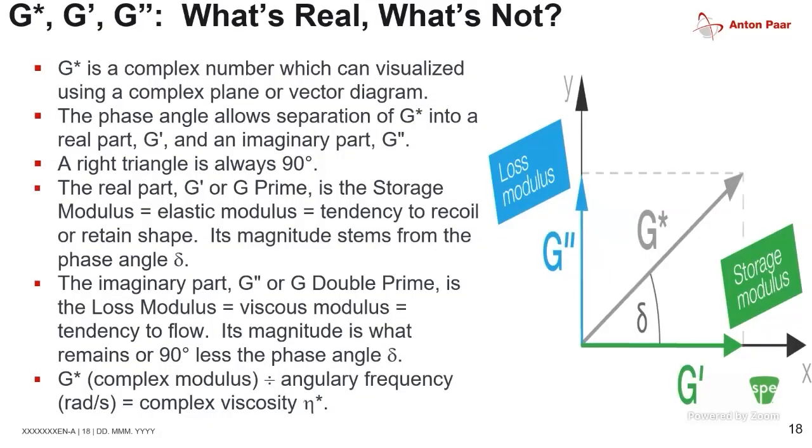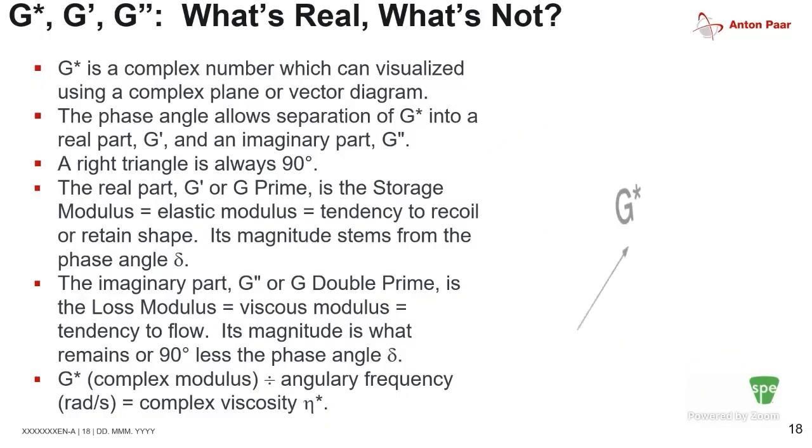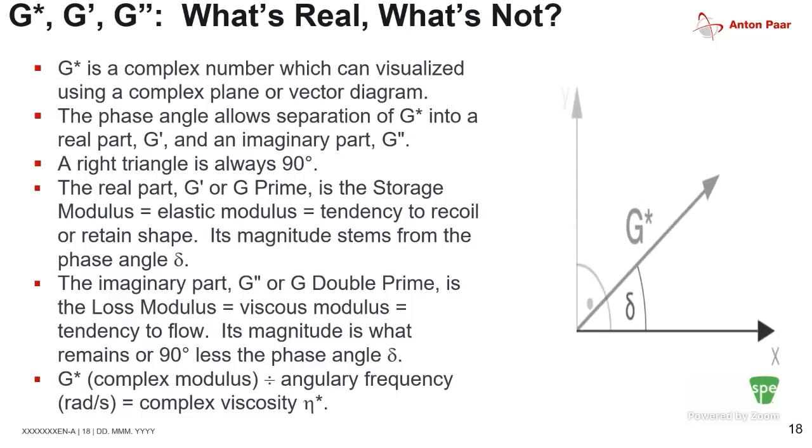And so from this, we introduce a series of parameters. We have the stiffness, which we call the shear modulus or complex shear modulus, which is G star. That comes from the stress and the strain response from the sinusoidal behavior. And from that, we can break it down using vector math, where the stiffness is the modulus. We know the phase angle from how far apart the stress and the strain are from each other.